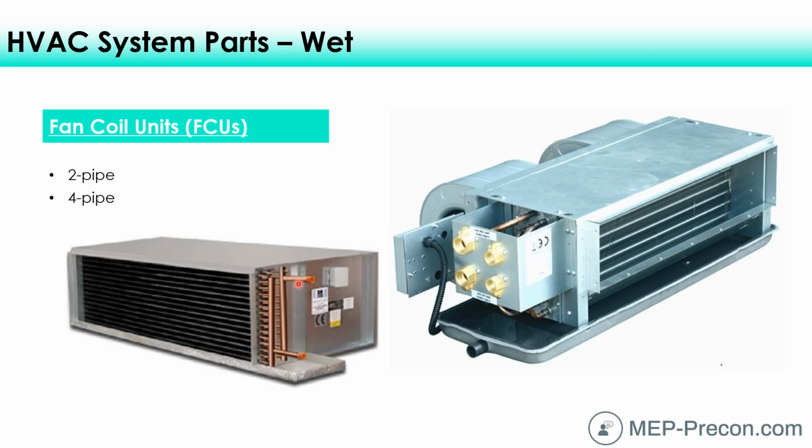And maybe you have a seasonal changeover, meaning that sometime depending on where you live, maybe October, it's going to get colder to the point where the plant engineer comes and turns off the chiller and turns on the boilers, and so now everybody gets hot water or heating hot water within their fan coil units. And if somebody still needs cooling, well, they're just going to be a little bit upset. And then sometime in, I don't know, March, April, they do the reverse, and they turn off the boiler and turn on the chilled water system to provide cooling. And if somebody still wants heating, well, they're just not going to get it.